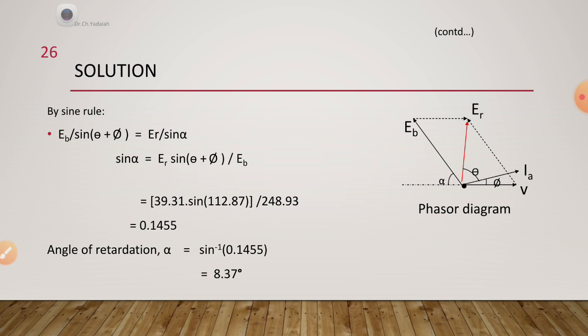That is the angle between the stator magnetic axis and our rotor magnetic axis. The angle difference is 8.37 degrees at this condition. It can be a maximum of 90 degrees, but now only 8.37. Both are coupled: the stator magnetic field and rotor magnetic field are coupled. It is running, but the loading angle is equal to 8.37 degrees. This is the value. Okay.